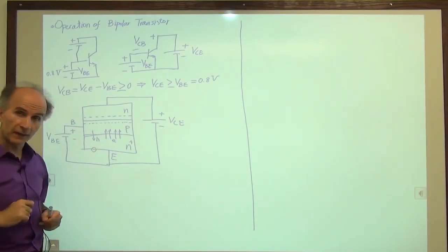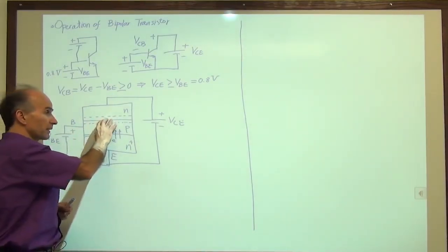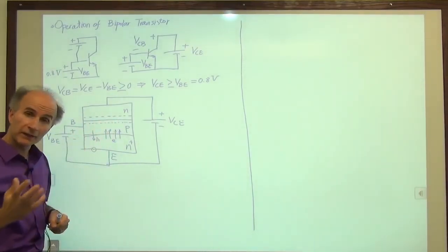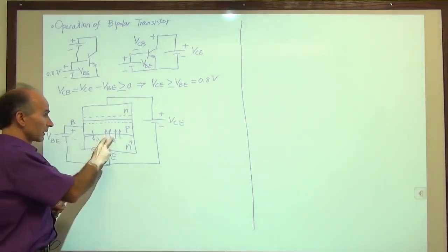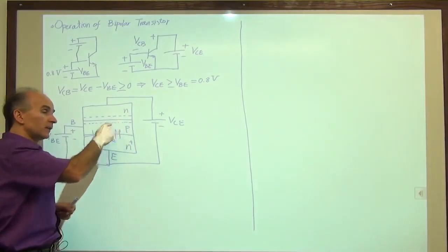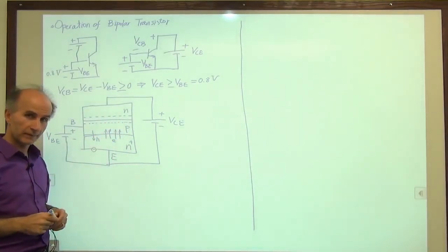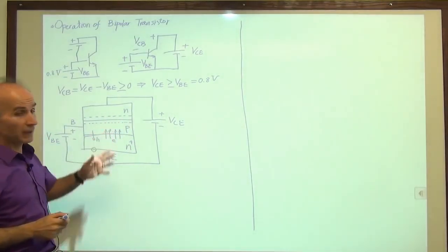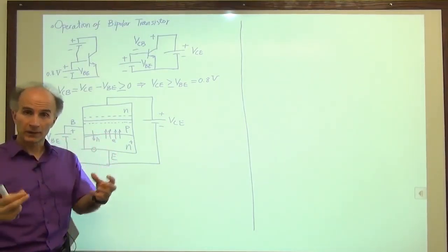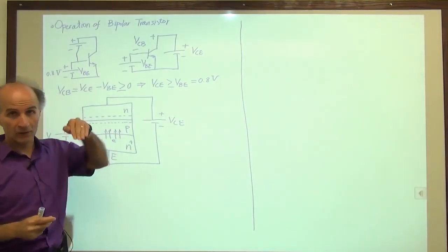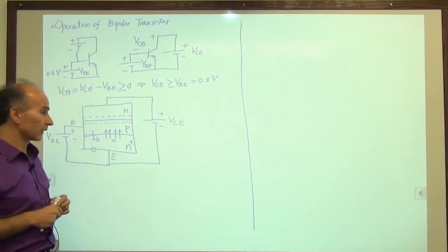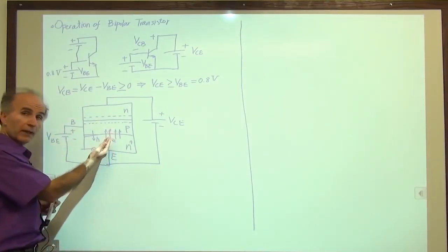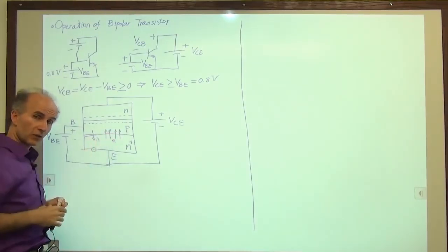Now that is very interesting. We have a reverse biased junction that actually carries current because we are injecting some carriers from outside into its depletion region. This is not something that we would have seen in a simple diode, right? Only with an external injection into the diode could we have a scenario like this. Now this external injection is automatically provided by the emitter-base junction.